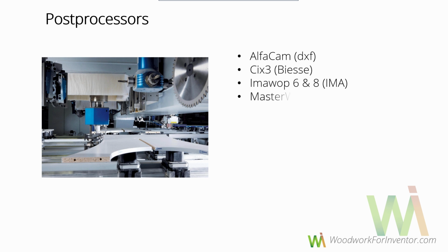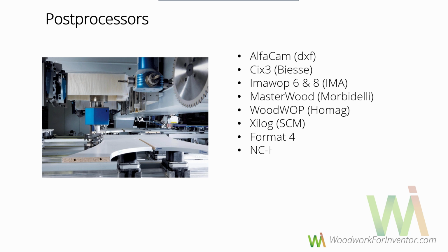The next question is about the postprocessors. So just a few more words about what the postprocessor is and how it works. The postprocessor works like a translator between the Woodwork system and the exact CNC machine. We can automatically analyze the geometry and find out if it is possible to produce the geometry according to the CNC